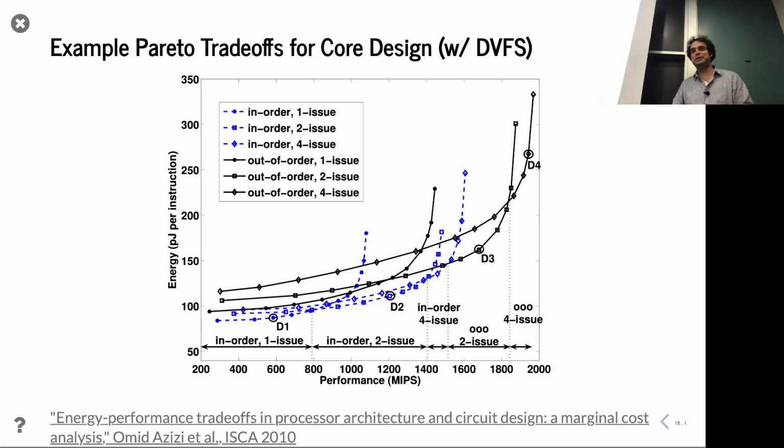Change your voltage, change your architectures, change your array dimensions, change how many bits you have per mat, change your decoder design. This is doable. This could be done, right? And you can see, you know what? If I have a 256-bit mat versus a 512-bit mat, 128-bit mat, you see which one comes up with certain parameters. And so you can get this. And so if you can get enough points, these curves emerge.